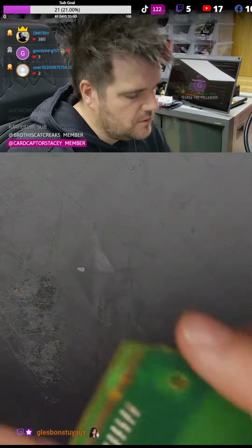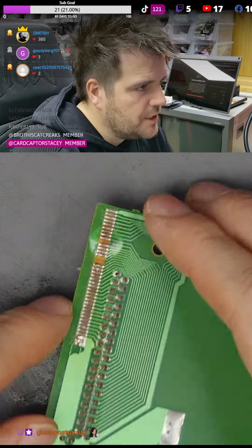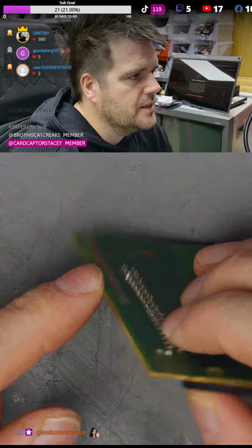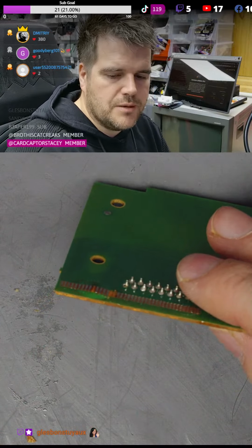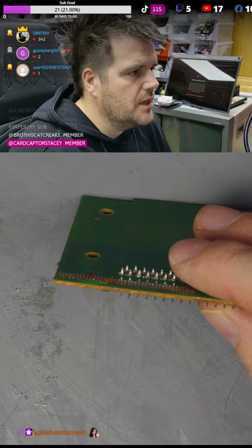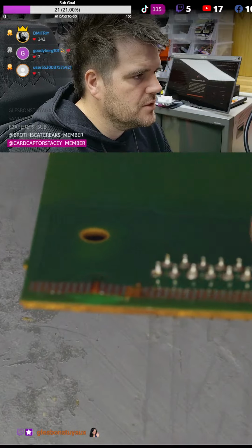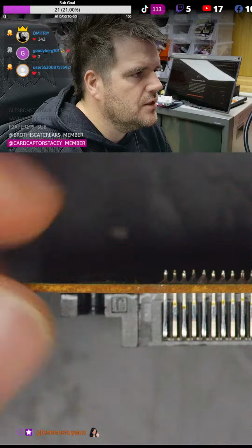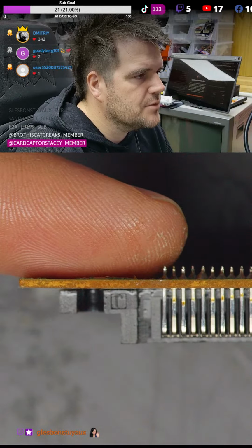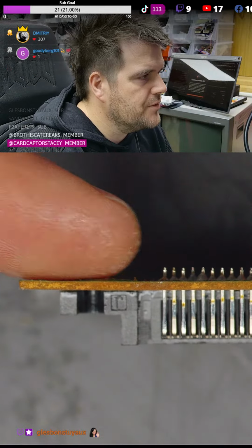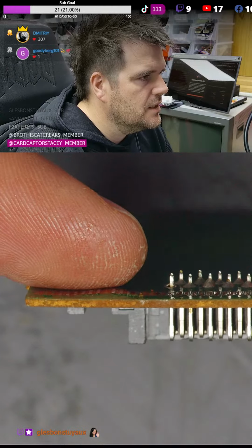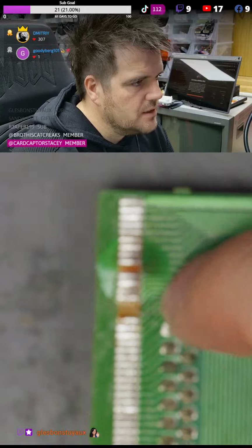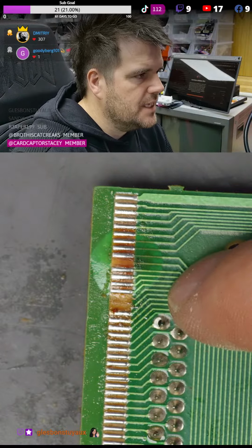You can see it's also already, that's the popcorning I'm on about. So that's the part where we use the soldering iron, and this is what I'm on about all the time with boards where they can popcorn. And this is also a paper board, so you can't really see much and it's not going to damage much, but there's a little bit of a hump there now, very small. You can just about see if I put my finger there, there's a little bit of a hump there. You can normally pierce and flatten these down to get it sitting flat again.